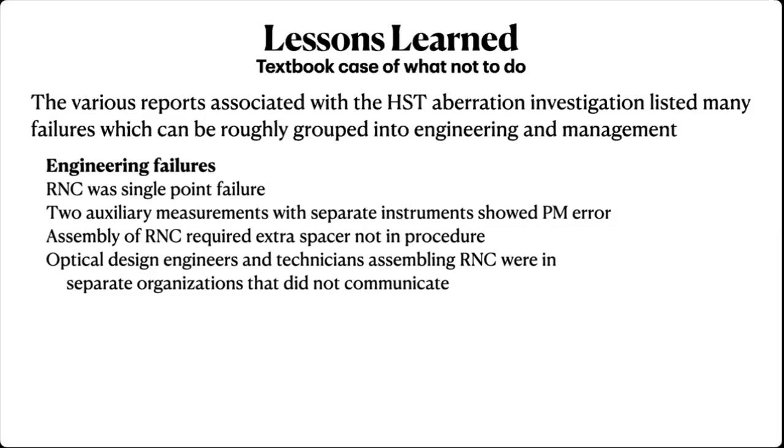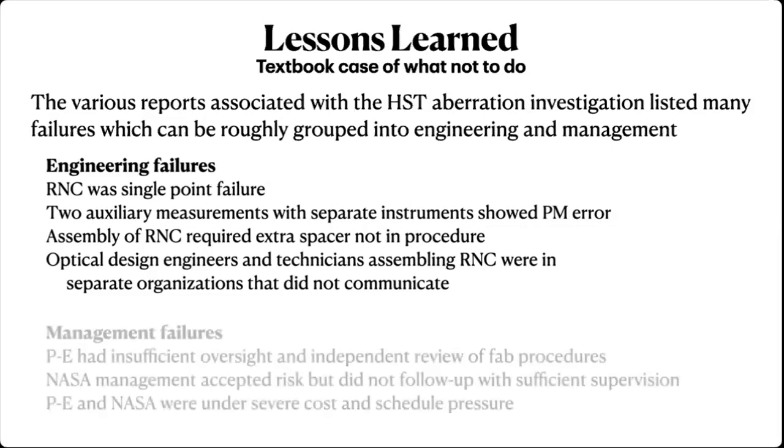The fact that it required an extra spacer when it was put together also seemed to have eluded attention. Normally in that case, if you're following a procedure and you have to do something that's not in the procedure, you stop. The technicians doing the work should have consulted with optical engineers and figured out before they continued what the issue was. None of that was done. The other was a sort of functional problem, that the optical engineers were in one organization and the technicians putting the reflective null corrector together were in another organization. There was not good communication.